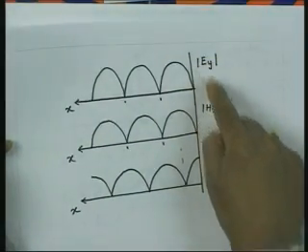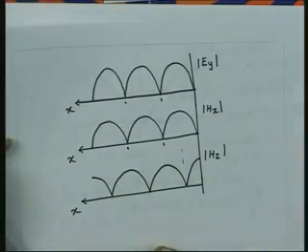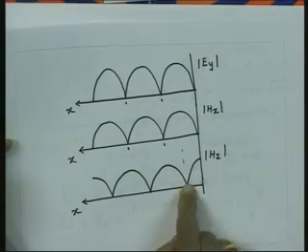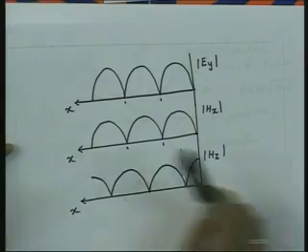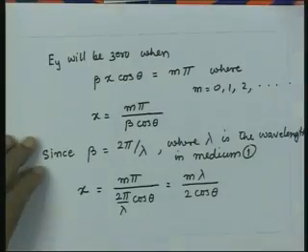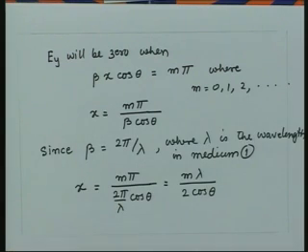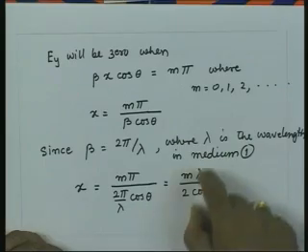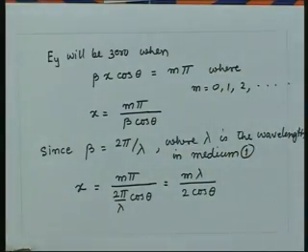So, E y will be 0 and H x will be 0, and in those planes H z will be maximum. If I go by a quarter cycle away, then H z will be 0 and these two quantities will be maximum. So, essentially we are defining some kind of a wavelength in the direction perpendicular to the interface, which is lambda upon cos theta, and if I go lambda by 2 of that effective wavelength, at that location the field will be 0.